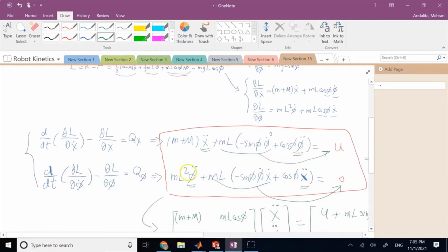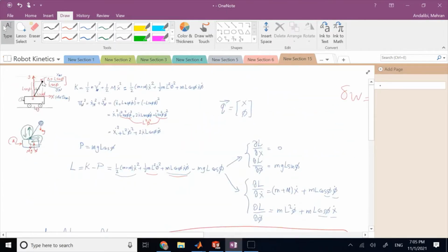You can always skip internal reaction forces and couples that do not do a net work. So it's very similar in that aspect to the work energy method, when you consider the whole thing as a system and not individual components, and that will eliminate a bunch of unknown reactions that you don't care about, as well as you're dealing with energies and scalars, not with vectors, right? So that's the beauty of this Lagrangian method.